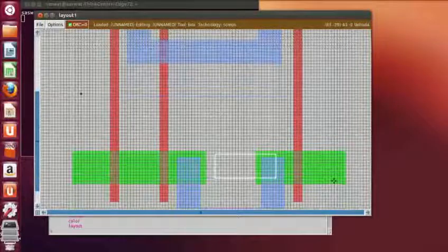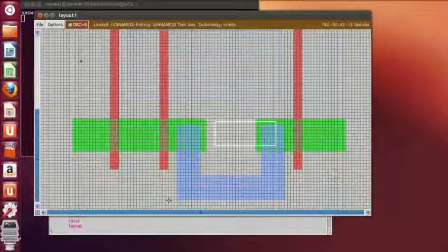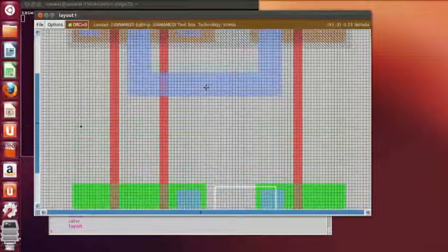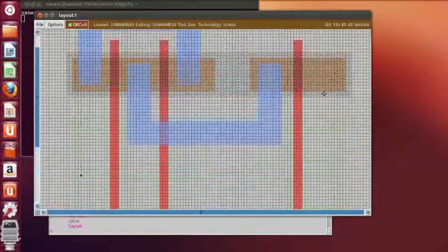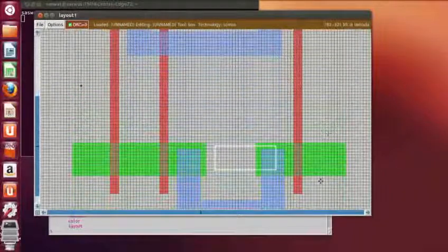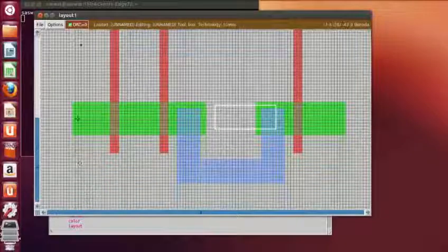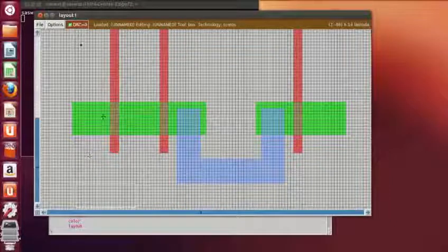So from where will we obtain the output? We will obtain the output from the common drain point of this third PMOS, third NMOS, and the first NMOS, as we have seen from the schematic itself. So at first we'll short these two.